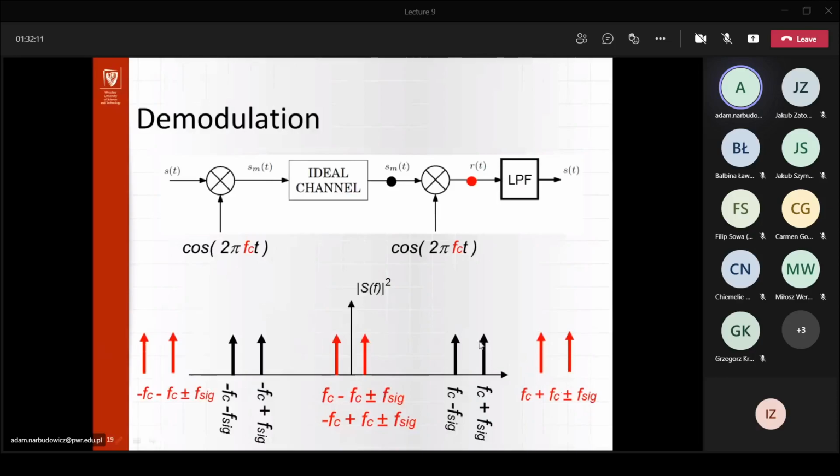And of course, we are interested only in our baseband signal, because that's our slowly changing signal that we can process. This is pretty much trash. This is double the original frequency that we are transmitting. For example, if you think about 900 megahertz of the mobile signal, this would be 1800, which might interfere with other communication.